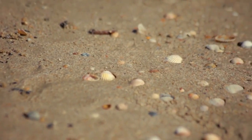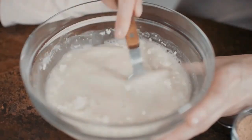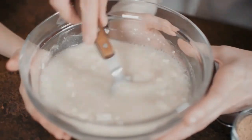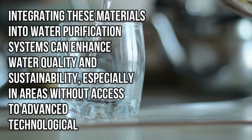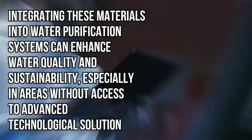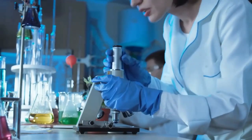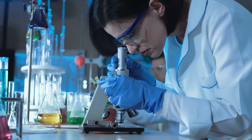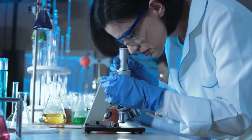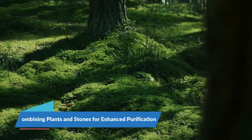Stones and minerals provide a versatile and effective method for water purification, serving functions from basic filtration to complex chemical reactions. Integrating these materials into water purification systems can enhance water quality and sustainability, especially in areas without access to advanced technological solutions. Their natural origin and capacity for reuse or recycling also contribute to their appeal in sustainable water management practices. Combining plants and stones for enhanced purification.